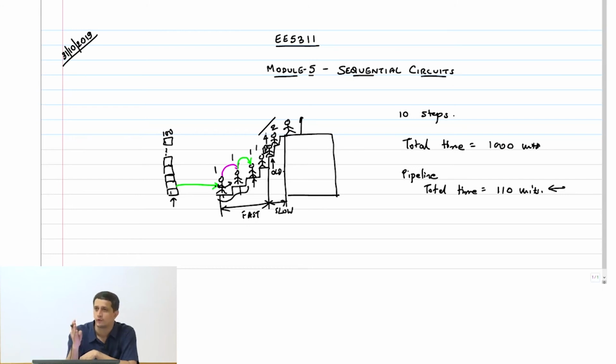You keep one brick at time equal to t equal to 4, right? That guy takes 6 units to take that and finish it, right? By then 4 units has come. So clearly at some point, because this delay of 6 units is larger than 4, you are going to have more than one brick on that in-between pedestal, right? It will take 4, 8, 12. So somewhere at 6 and then at 12 maybe you are going to have a problem, or some later time. So therefore I have to wait for the slowest path in my system before I can feed the next data or the next brick into my pipeline system.